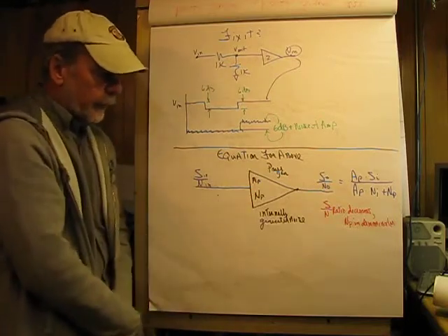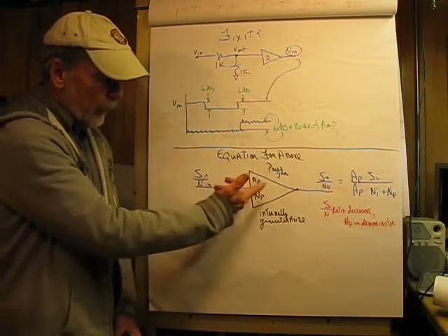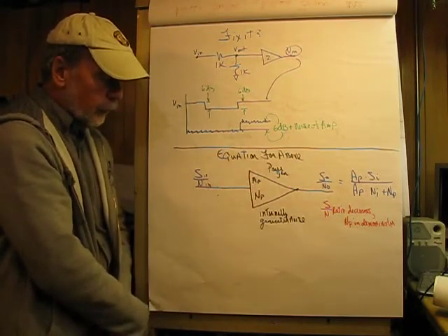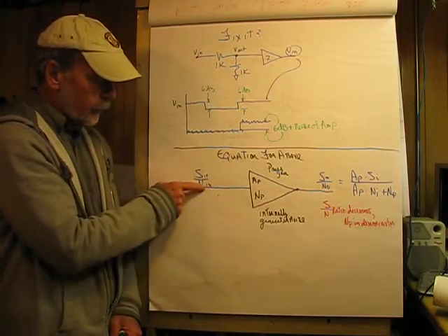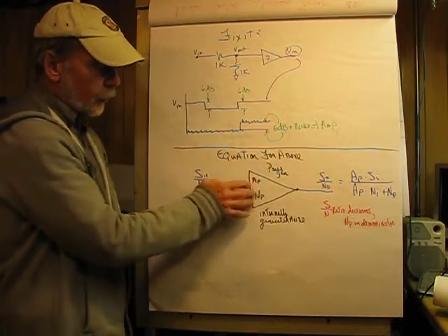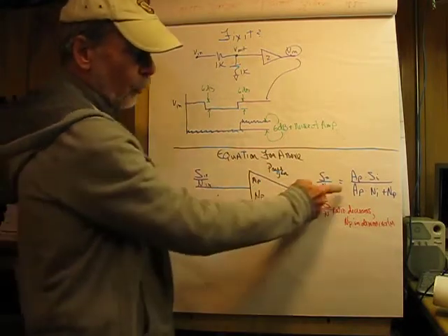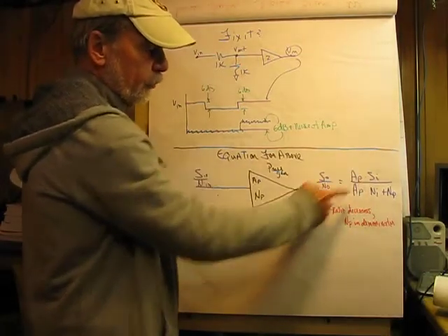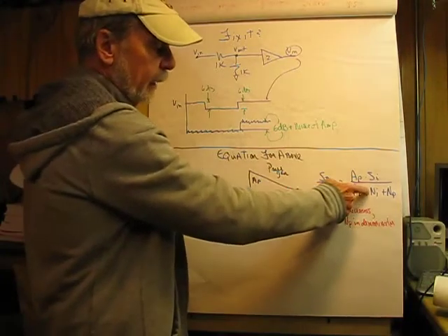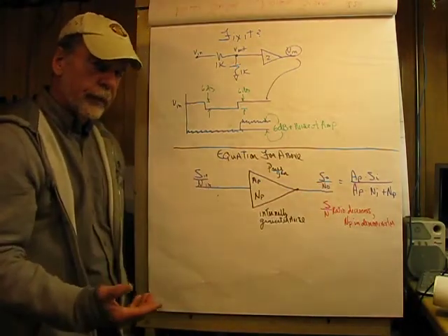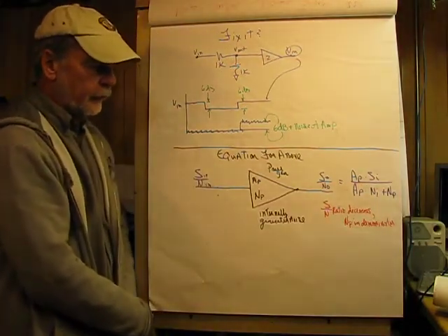And we have an amplifier, and that amplifier is not perfect. It has a power gain, and a noise voltage contribution here, and this is the signal to noise input, and it goes through this amplifier and it is degraded a little bit, and then the output would be the gain of the amplifier times the signal, which we would expect, divided by the gain of the amplifier times the noise, which we would also expect, plus the noise component of the amplifier itself.